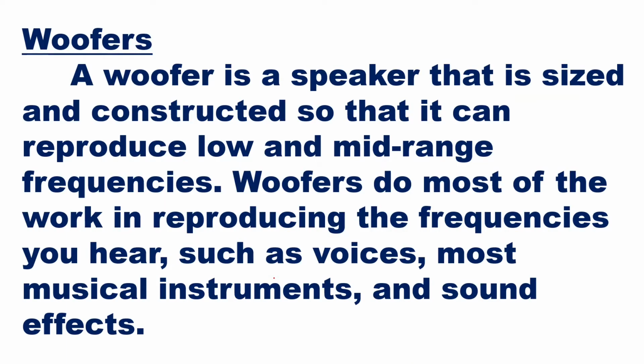So if you see the construction part of it, a woofer is a speaker that is sized and constructed so that it can reproduce low and mid-range frequencies. Woofers do most of the work in reproducing the frequencies you hear, such as voices, most musical instruments, and sound effects. Now, for handling low frequency, the size of the diaphragm also should be big.